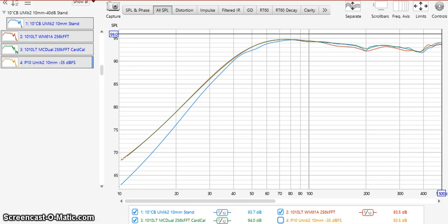So one of the recommendations was simply to calibrate that against my other systems that I believe were correct, at least below 100 hertz, which is where the issue was. Starting with about 80 hertz, it started to diverge. I could easily just go in and do this adjustment to the correction calibration file for the UMic and be done with it, but that didn't satisfy me. That didn't sound like the way to go. So I've spent quite a bit of time since then trying to figure out what the problem is. I think I have found that.